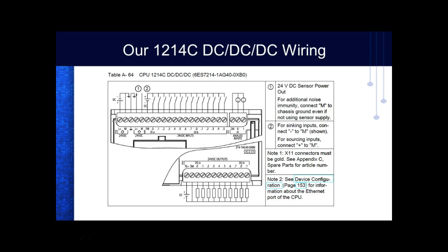And we have to have this guy right here generates its own power supply. So EMs, by the way, I'm sorry, these guys right here have to have their own power supply. So they're going to generate a voltage between 0 and 10 volts. And how you wire those up depends on the actual device itself. But notice I have no option here. So my common goes down through all my inputs. This is going to connect to EM. So the way Siemens is set up, L is plus DC, M is minus DC.